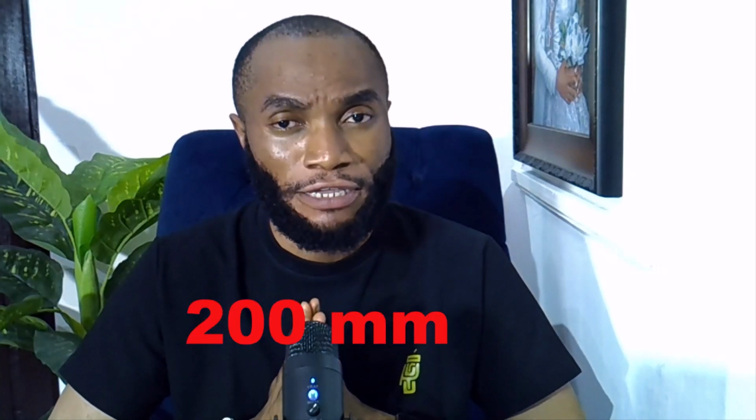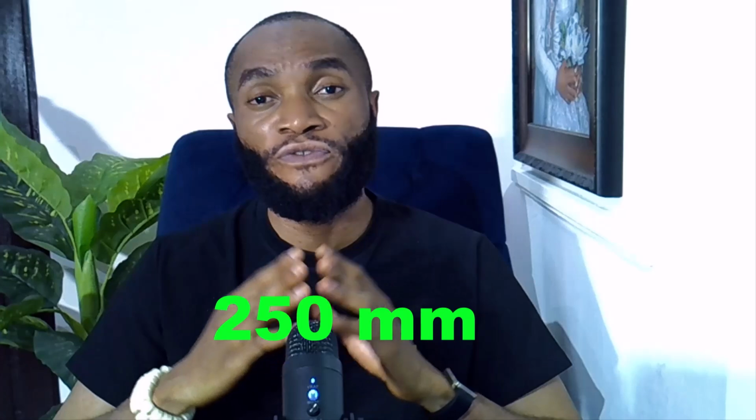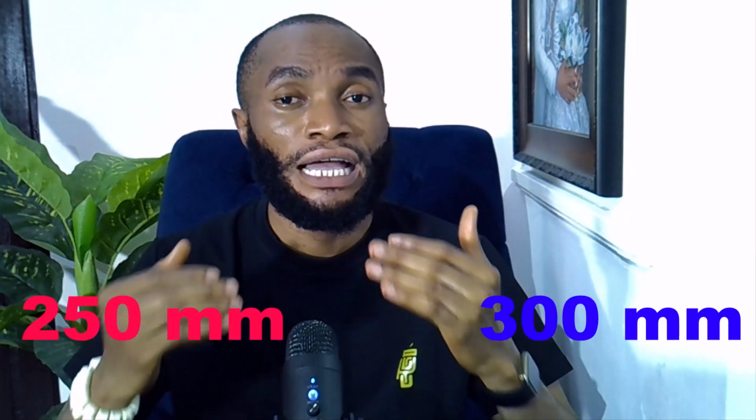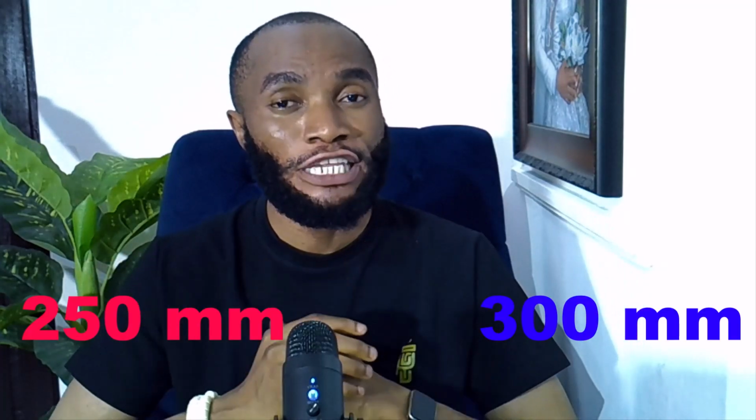Now when it comes to flat slab design, the minimum depth of a flat slab is 200 millimeter. But even if 200 millimeter is the minimum depth, it is not commonly used. The minimum depth that is commonly used is 250 millimeter. Most people go ahead to use 300. So 250 millimeter and 300 millimeter are commonly used for flat slab design. Okay, that's fine. That's for the depth of slab.